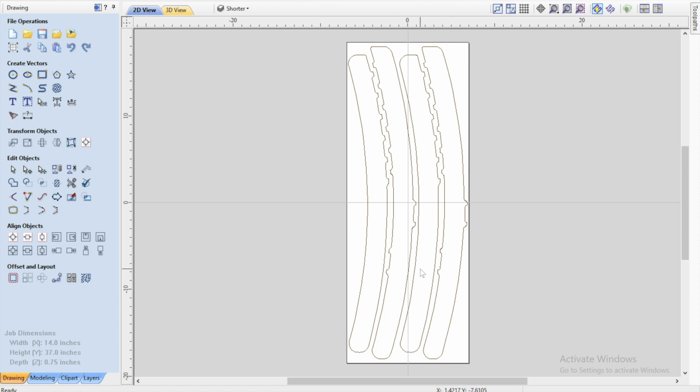As you guys imported this file, there's nothing to do editing wise, so we don't need to cover that right now. To select all of the items, you can either select them one at a time and then hold the Shift key to select multiple, or you can click down here on the bottom and move up and left. Anywhere that the rectangle touches will be selected, and that selects the entirety of the drawings. We want to create a tool path, which means the file that the CNC is going to use in order to cut out the pieces.